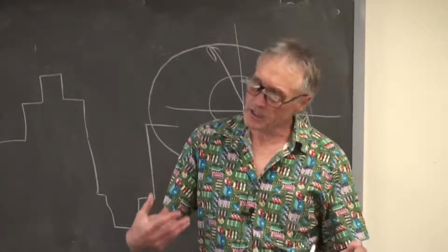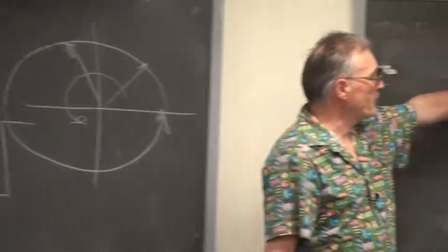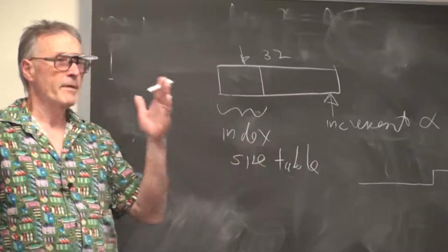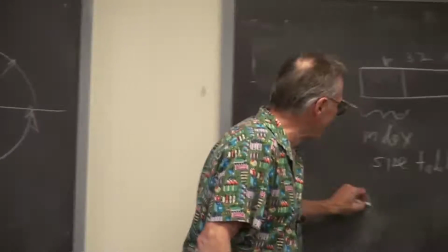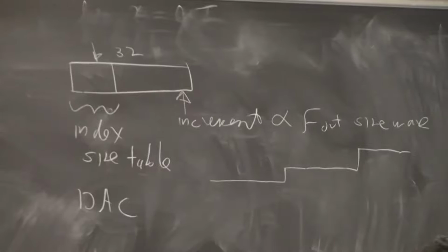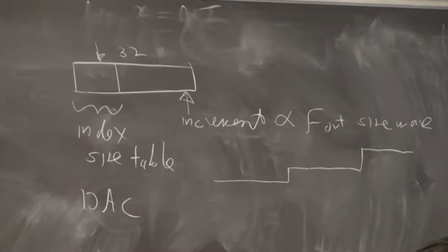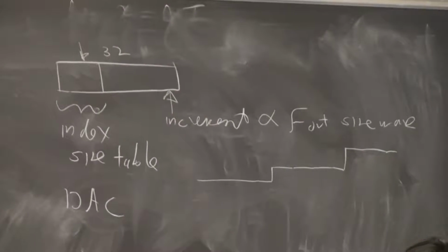So the whole DDS generator is going to be 2 lines of code. We're going to increment a variable. We're going to do a table lookup. Then there'll be another line or 2 which actually transmit that value to the DAC, because we have to do some sort of manipulation to get the SPI to run. That's it. Oh, we have to build the table, but that's done once in main, where you can afford to do a lot of floating point arithmetic.